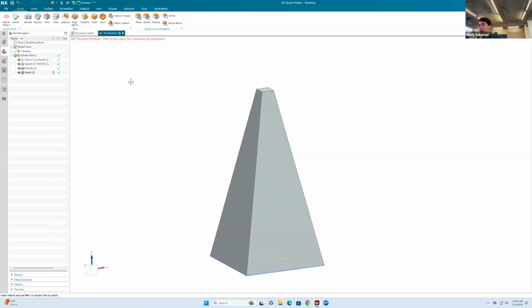The next step is not trivial, and it's related to creating planes. So we're gonna click in where it says datum plane. And as you can see from here, there's a bunch of different ways to create a plane. The reality, maybe if you've taken math, I'm assuming vector calculus, right? You guys do plane math in there. You can define a plane with 2 vectors, or maybe a vector and a point, right? You click a point and the vector is perpendicular. It's literally that. It's quite fun. So the one that I like the most is called point and direction.